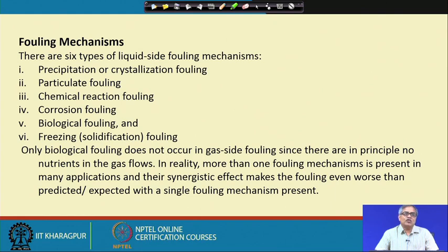Then freezing or solidification fouling. Freezing is also one thing, that if the temperature goes below, sometimes freezing occurs. So, obviously, ice crystals will form and choke the passage. So, this is also one kind of fouling. Now, these are the fouling mechanisms. One can elaborate on all those mechanisms, and the book which I have mentioned, you can go through that book if you want to get some details of each of the fouling mechanisms. In other books also information is available, but